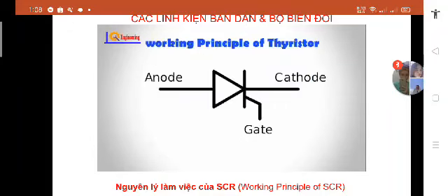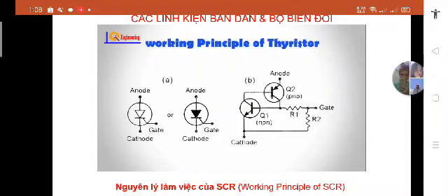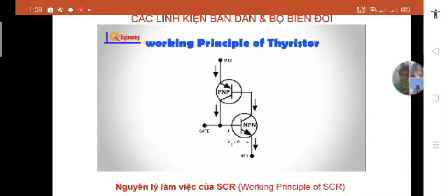Basics. Working principle of thyristor. The thyristor or silicon-controlled rectifier, SCR, is a device that has a number of unusual characteristics. It has three terminals: anode, cathode and gate, reflecting thermionic valve/vacuum tube technology. As might be expected, the gate is the control terminal while the main current flows between the anode and cathode. As can be imagined from its circuit symbol, the device is a one-way device, giving rise to the GE name for it, the silicon-controlled rectifier. Therefore, when the device is used with AC, it will only conduct for a maximum of half the cycle.